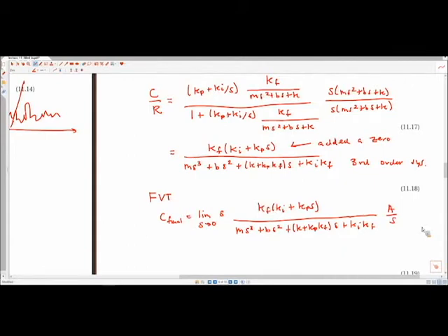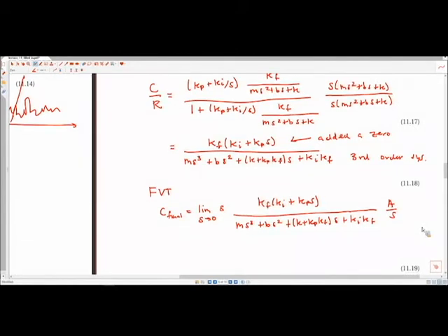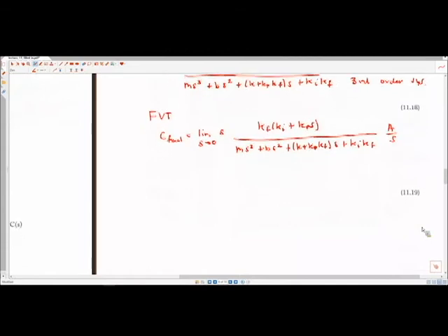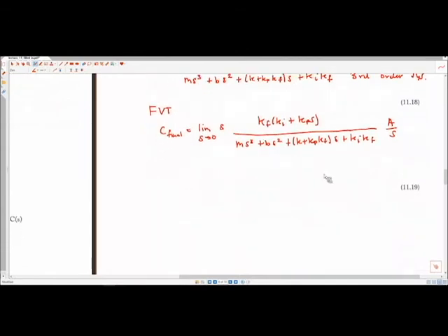Yeah, so I think what you are hitting on here is one of the most dangerous parts about integral control. Just so everyone's on the same page, another doodle here. So you're saying that if you have some sort of system where for whatever reason the error signal is just held, right?